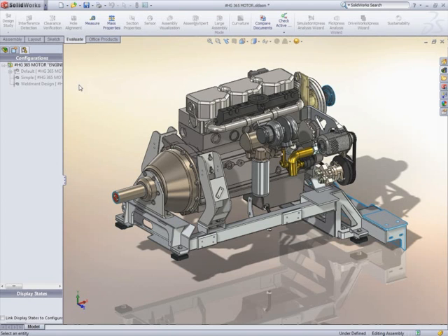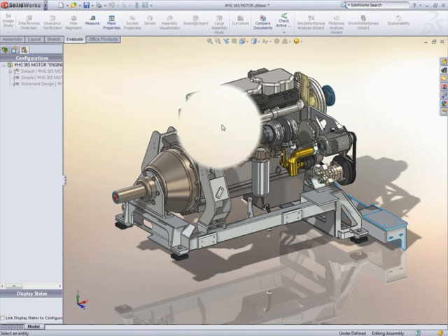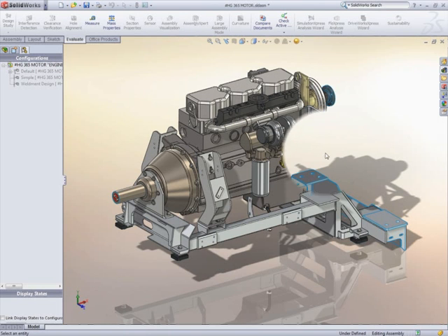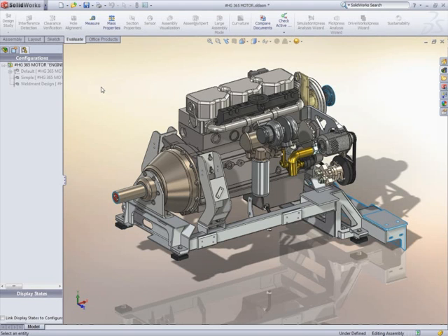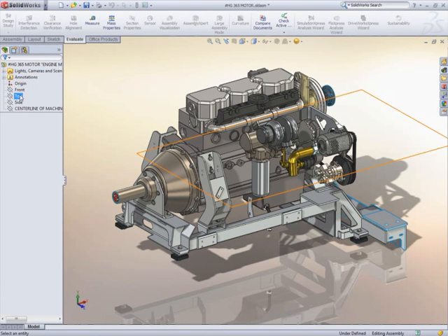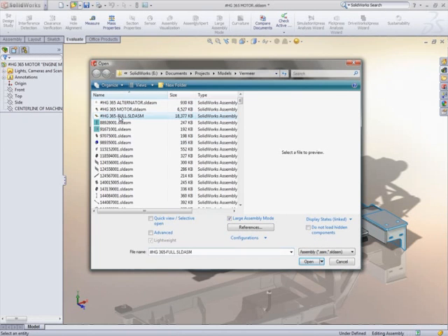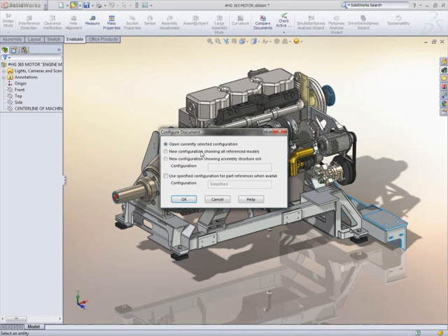Doesn't look any different? Well, it does when you move the mouse over the assembly. The faces that don't really exist are removed, so we can clearly see which faces have been included and can be referenced in the top-level assembly. Notice also that the assembly file has no parts, making it extremely compact, easy to email, and impossible to reverse engineer. Now let's open the main assembly, this time using the advanced option.